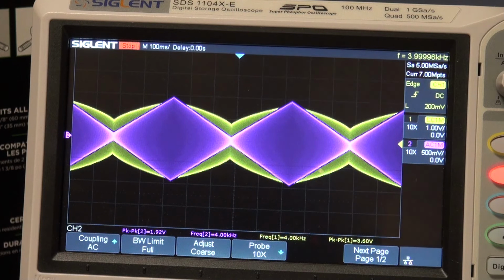So what's happening is, from this graphic you can see that the input signal is changing a great deal as far as amplitude or strength, whereas the output signal of this AGC circuit is not changing as much. It's more compressed. The dynamic range is compressed. So this is kind of exactly how we would like this to work, and it appears to be working that way.